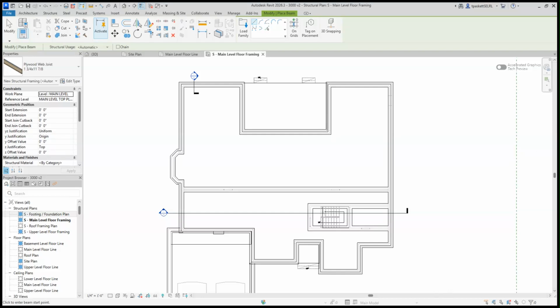So we're going to try, and I go with the larger dead load so people can put more weight on their floor. And I need to go 18 feet. Well, if I'm going 16 inches on center here, and I'm using 11 7/8, at a 210 option, I can span 19.4.